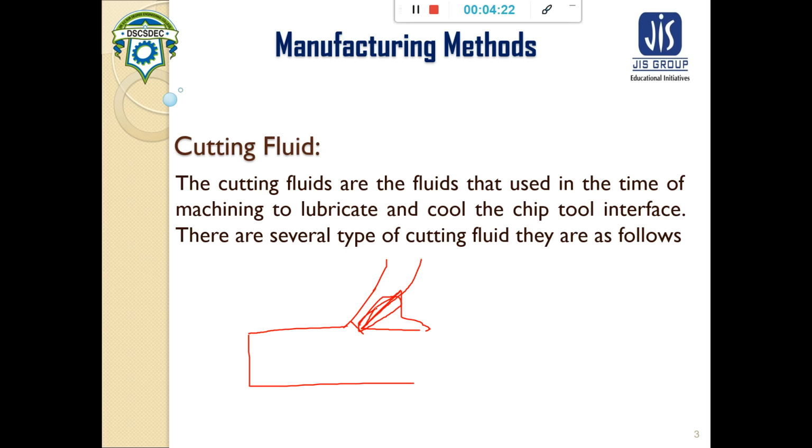But there is some machining technique especially for the ceramic tool material. When the tool is ceramic, we do not need any external cutting fluid to lubricate, because the friction at the chip tool interface will be very little.